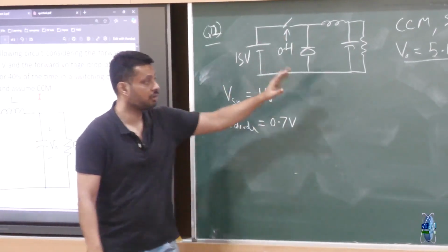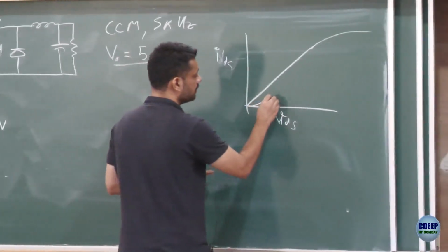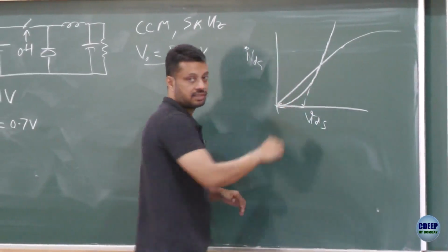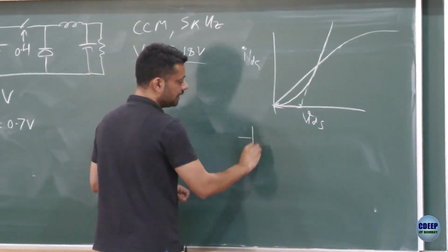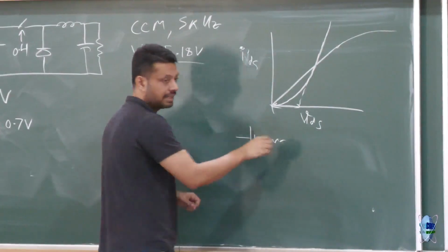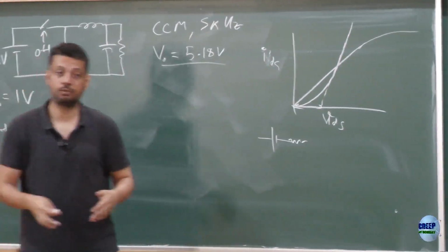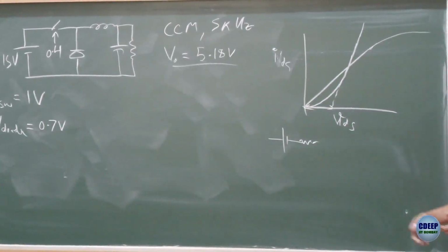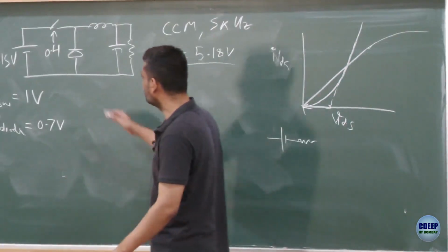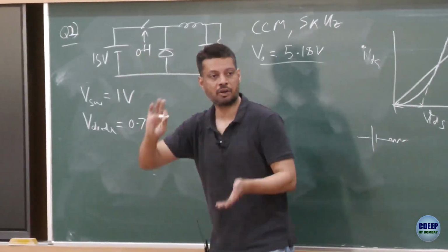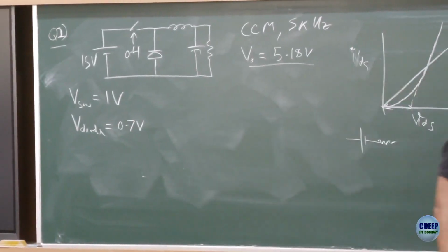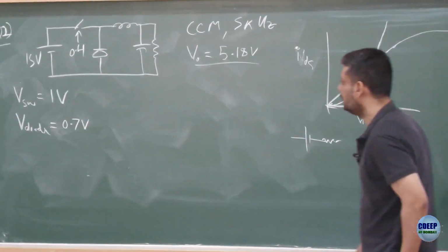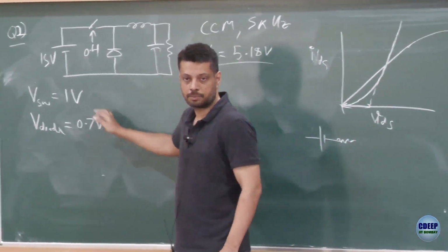And similarly, the diode characteristics, if you remember, this is how it looks, right? It's a combination of a voltage drop and a resistive component. So the diode you can usually model as a 0.7 V drop and a resistance. If you push large current, the voltage drop will no longer remain 0.7, it will become 0.8, 0.9, 1, 1.2 depending on the diodes, right? So in reality, drops are modeled as a combination of resistance and a fixed voltage source. In this question, just to simplify it and give you a flavor of that, we have only told you that these are fixed voltage drops, right?